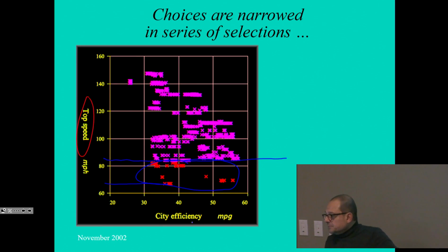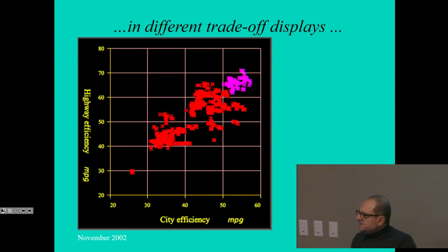By the way, what do you think is the cause of that? I say gearing. I think this is all transmission and final drive related. That is, the gearing is short, so it'll give you good acceleration, but it won't give you top speed. So we eliminated poor gearing choices. Now, I have eliminated anything that does not have sufficient acceleration and does not have sufficient top speed. I have now guaranteed that I have some criteria of performance that are acceptable. So I further reduced the set. This is a much smaller number now.